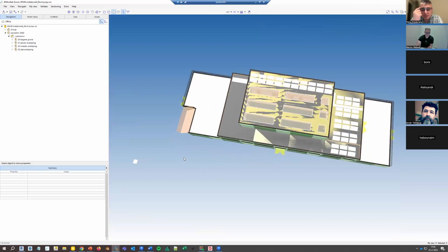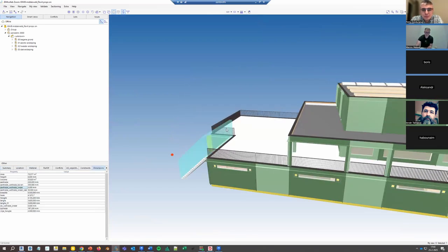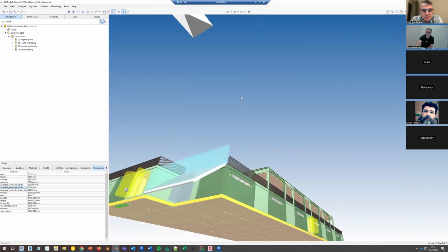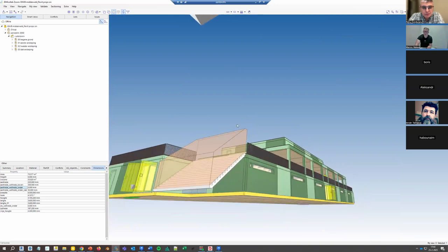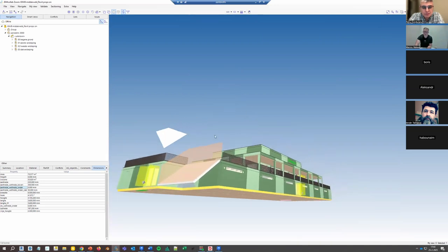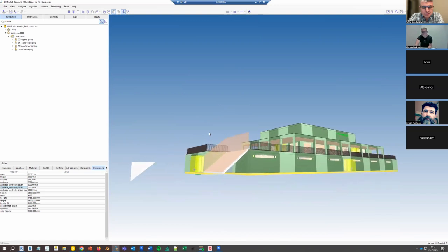Yeah, and well, this is of course outside, but usually on top of every staircase, every stair flight, we have this as well. Because this is really useful, because this is clash prevention instead of clash detection. That's why we put it in the models, so we can communicate with everybody. This is the height, and it's the regulations height. It's not just actual height; it's the height that is required by the regulations.